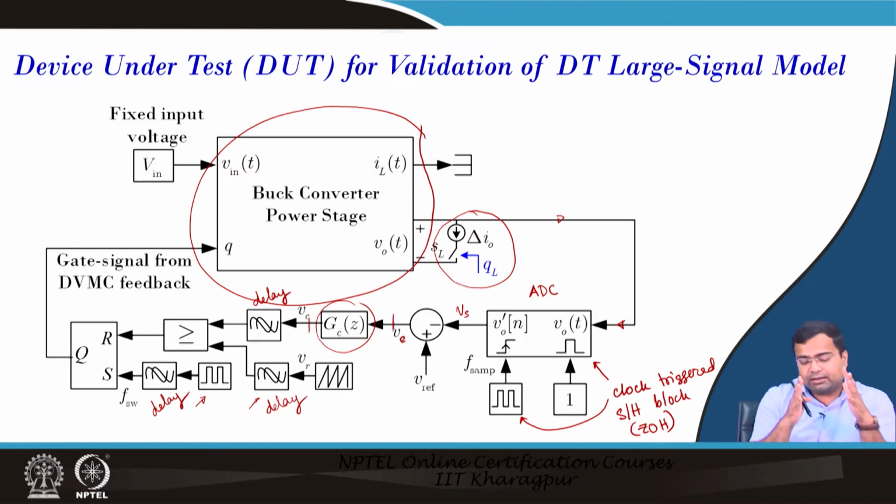So, that means we are synchronizing the switching clock with the sampling clock, and the switching clock is delayed by some Ts amount of time. Since the switching is starting after Ts duration, the RAM should also start with respect to the switching clock, and the output of the controller should be ready at that time. So, all delays must be consistent, they must be the same.